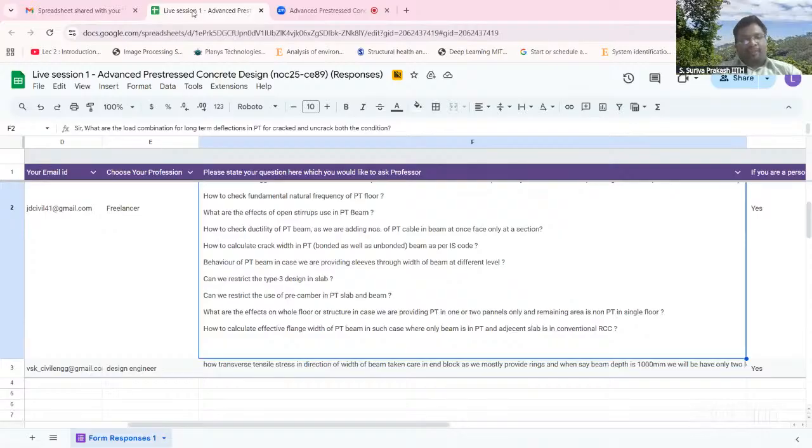This is the problem we are finding even in some of our projects. The design engineer does something, then the MEP consultant comes and does something. Most of the time, the coordination doesn't happen and mistakes happen. The MEP fellow will come and put it at a location wherever it's convenient to him, without really understanding the seriousness of the maximum locations of bending moment and shear.